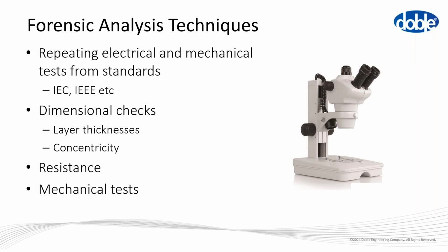And then lastly, and I've seen this in certain investigations, you may actually need to go back and repeat some of the tests that were done at the factory. Some of the tests which are laid out in IEC or IEEE documents. And if it's a cable, that can be just simple things like checking the dimensions of the cable, the thickness of the layers, the concentricity, etc.